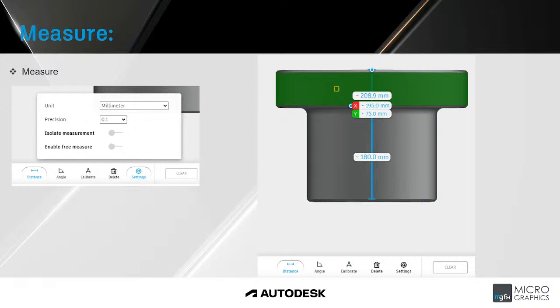Now let's have a look at the other tools that are available in the Autodesk Viewer. For instance, the measuring tool. Measure the distance between 2 points or an angle between 3 points. You can select the measuring units, for instance, millimeter, and the precision in the settings tab. That's just some of the options that are available. So if you click on your unit in the drop down, you'll be able to look in millimeters or inches and so on.